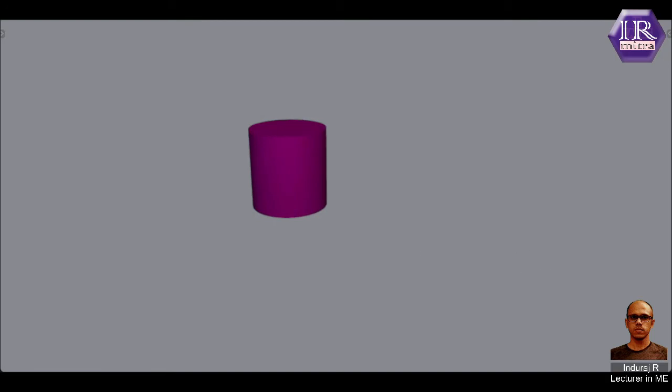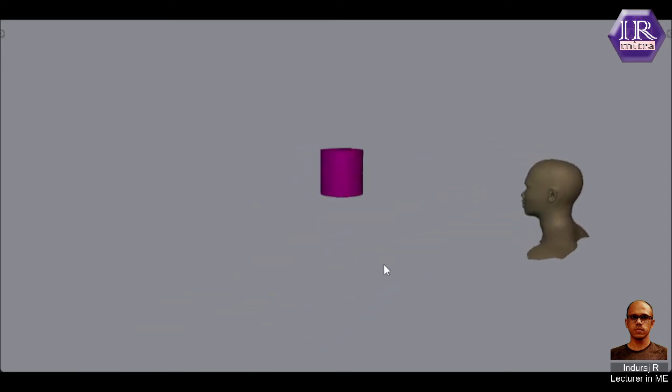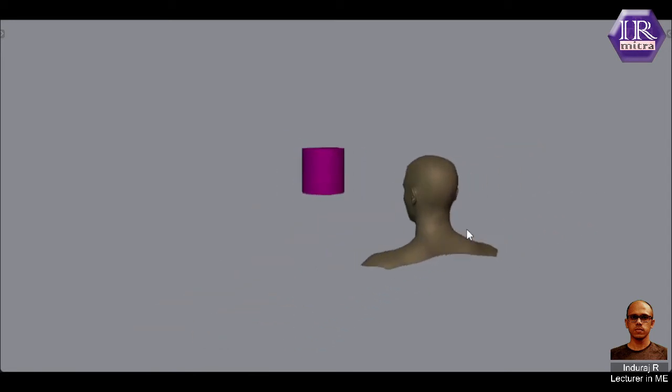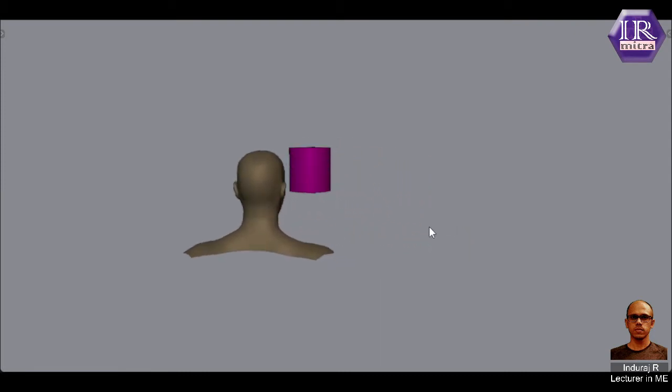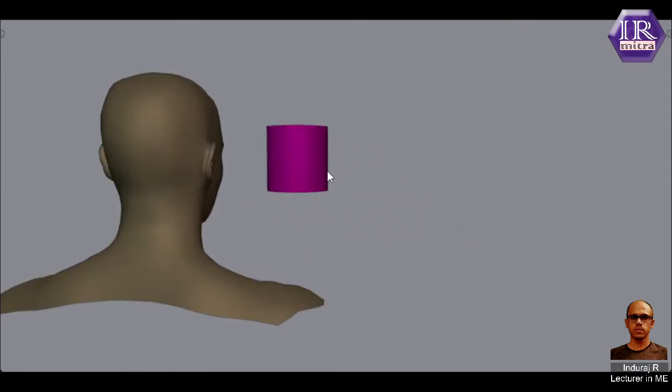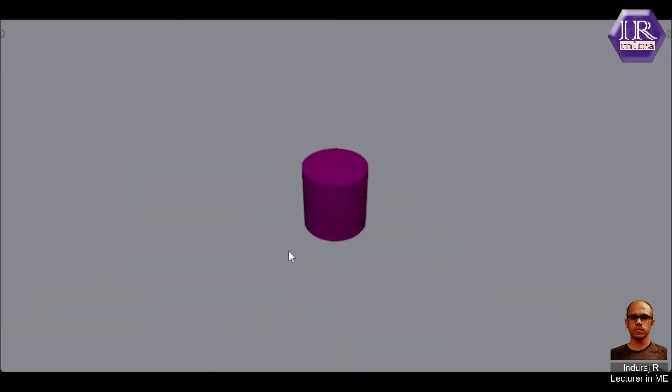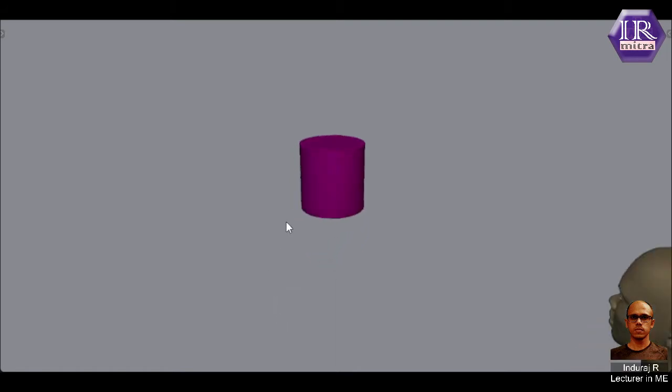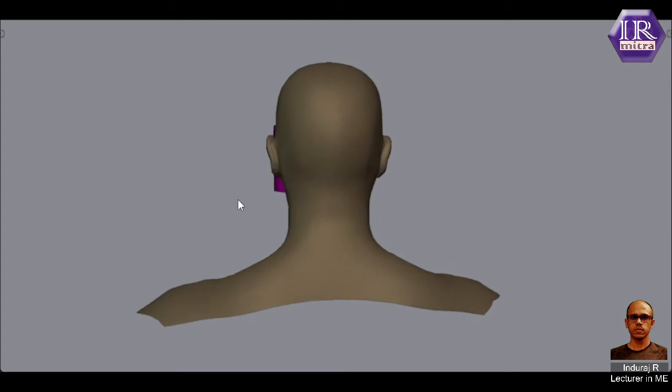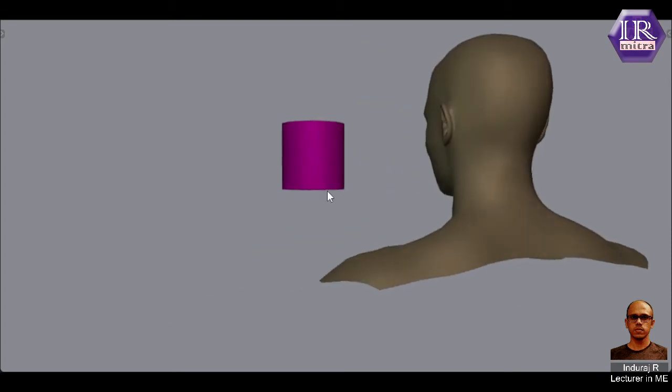And for this purpose, what we need is an observer. Suppose he is the observer here. When he is looking at the cylinder from this angle, what he is going to be drawing on a paper is a rectangle. But with this rectangle, the engineering drawing of this cylinder is not complete. So we will draw another view of this cylinder from above, which is going to be a circle for the observer. So by combining these two views, one can deduce that it is a cylinder.